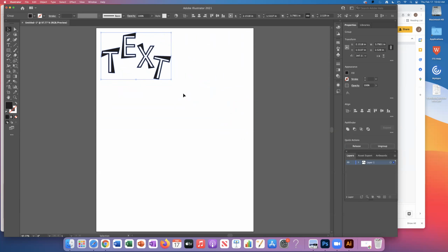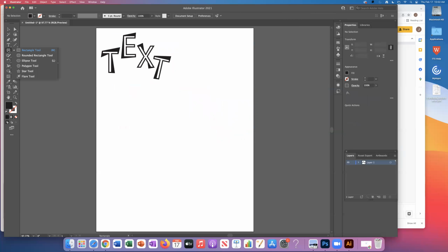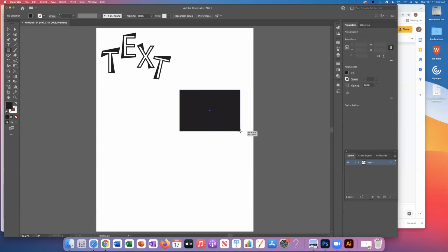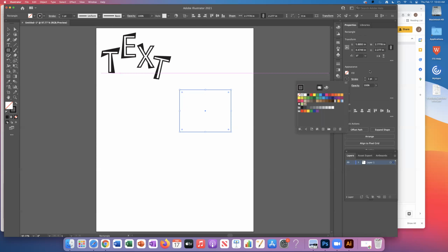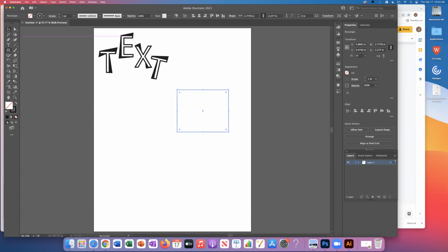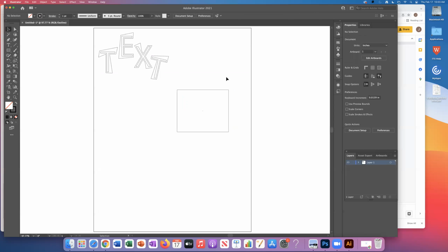That's another way that you may want to work in Illustrator, especially for this laser cut project. Here we have some basic shapes: rectangles, rounded rectangles, ellipses, polygons, things like that. When you draw with them, it automatically gives you a path, and it will typically have a fill without a stroke. So if I create a rectangle like this, it's going to add a fill. If I go no fill, and give it a stroke of 1 point, now we have our vector graphic. And if we hit the path view, Command Y, you can see that it's going to cut out the form